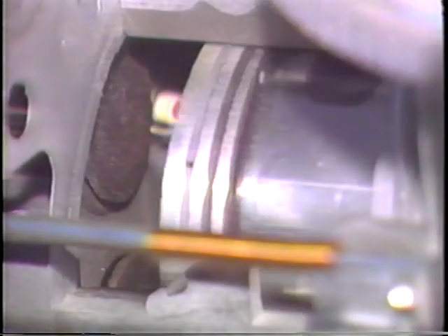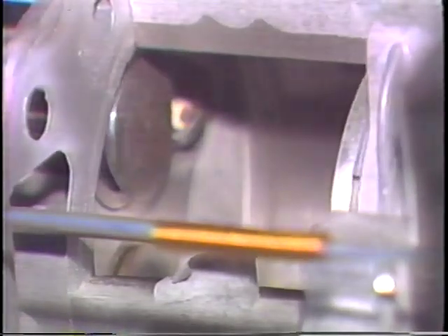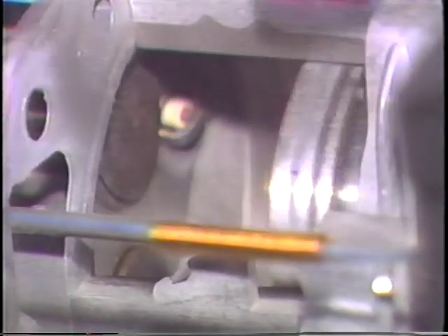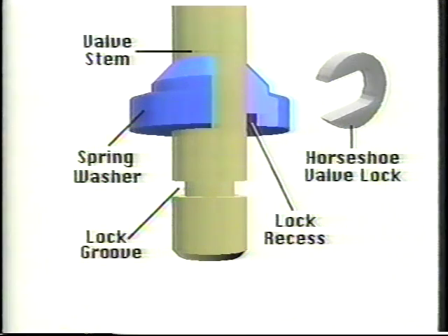A small gas engine valve train includes all the parts that open and close the valve seats or ports. The valve train must push each valve face off of its seat at just the right time in each of the strokes to cause flow in and out of the engine. In modern overhead valve engines, many of these components mount on the cylinder head. The valves, valve seats, valve guides, valve springs, seals, retainers, and valve locks all mount in an overhead valve cylinder head. With older valve-in-block engines, most valve train parts are in the cylinder block.